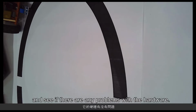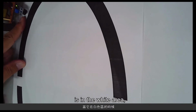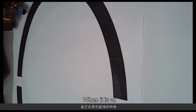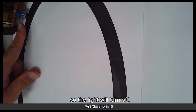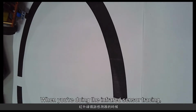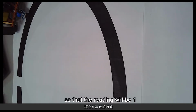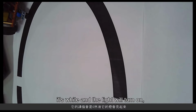Let's check the first one and see if there are any problems with the hardware. Let's have a look. When my infrared sensor is in the white area, the light should be turned on. It is 0 at the white area, so it should light up. When it is at the black area, its reading will be 1. So the light will turn off. When you're doing the infrared sensor tracing, remember that you must calibrate it so that the reading will be 1 when it's black, and it will be 0 when it's white and the light will turn on.